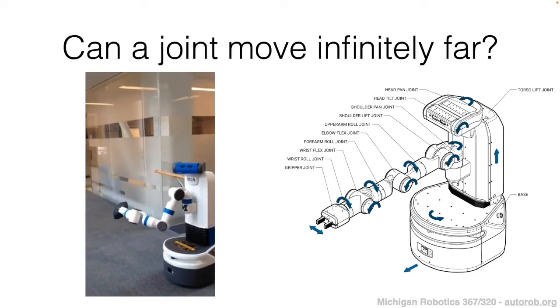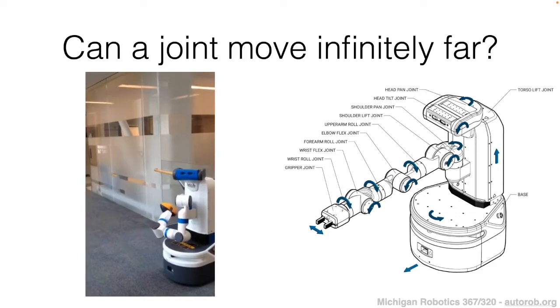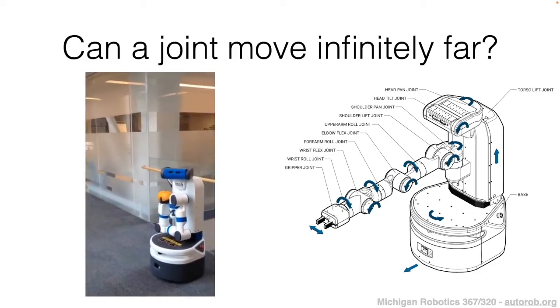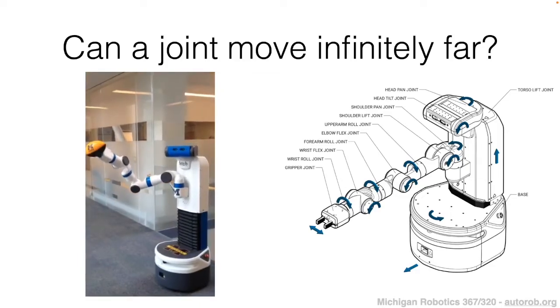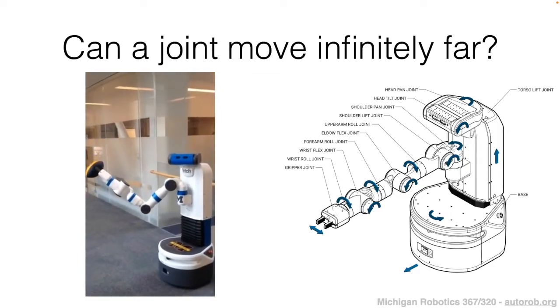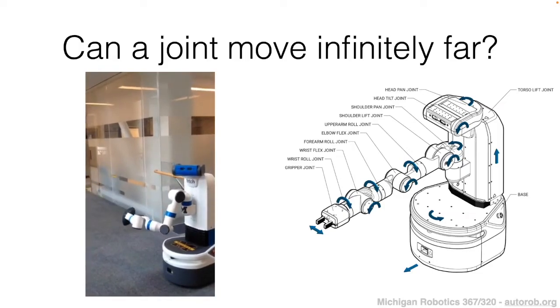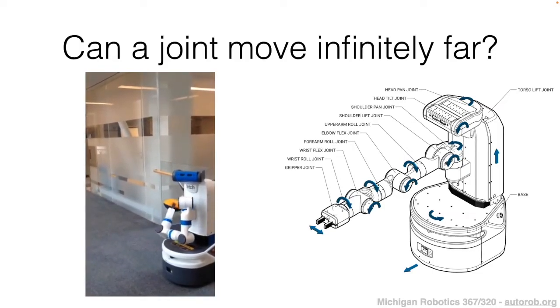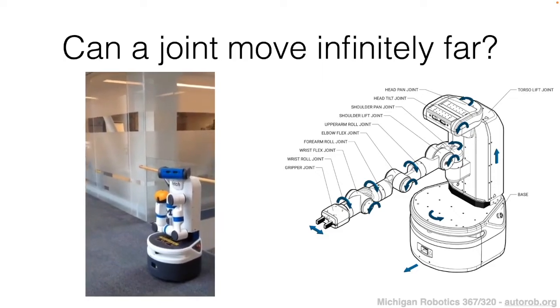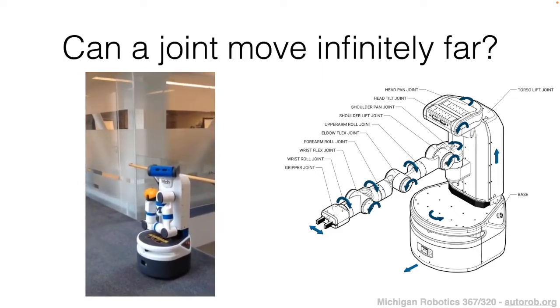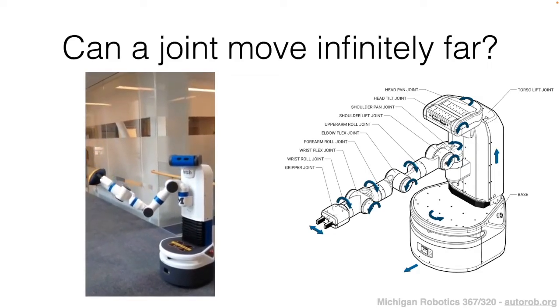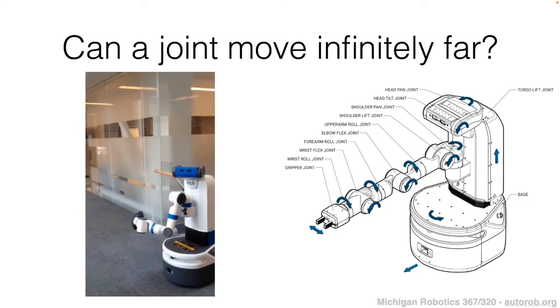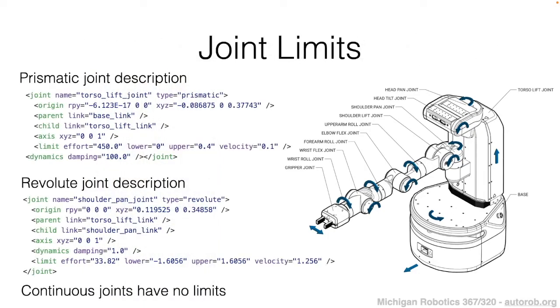On most physical robot systems, certainly the Fetch, each joint will have some physical limit beyond which it cannot rotate due to the intrinsic property of the joint itself, or potentially, which is something we'll look at further on in this course, if there are potential collisions with the environment. But internal collisions, so limits on the joints themselves, also have to be modeled within forward kinematics.